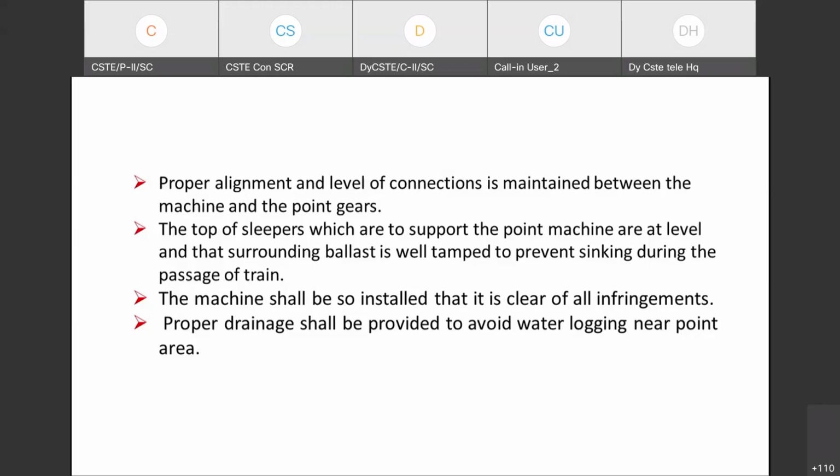Again, from the safety point of view, in some of the inspections, what I observed is that the CRS has checked the sealing over the detection contact. There is a transparent cover, and in one case the CRS observed that the sealing was not done. The CRS said that if sealing is not done, somebody can tamper with the detection contacts. So from the safety point of view, all the people involved in maintenance should ensure that the transparent cover covering the detection contact is sealed.